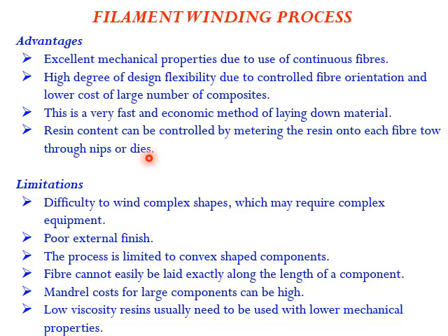As I said, the nip rollers are provided to control the amount of resin deposited on the fiber material. Limitations: it is difficult to wind complex shapes, because the density with which you wind these fibers on the mandrel is difficult to control when it is an irregular shape. Poor external surface finish. The process is limited to convex shaped components, so fiber cannot easily be laid down exactly along the length of a component. Mandrel cost for large components can be high.